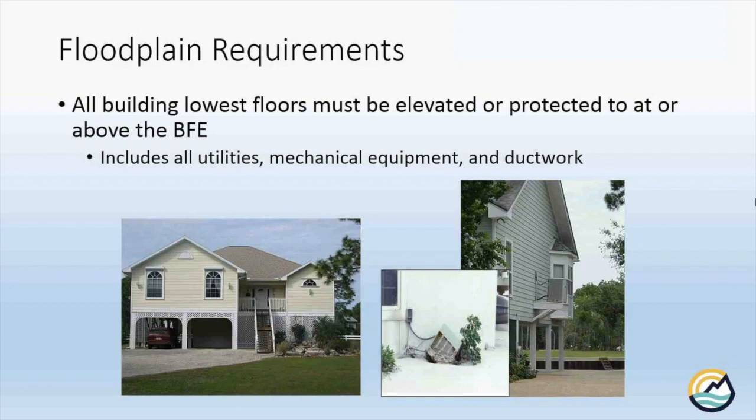Big requirement though, like I said before, all buildings' lowest floors have to be elevated or protected to above the base flood elevation. I'm going to say that again. All buildings' lowest floors must be elevated or protected to above the base flood elevation. So basically we want to keep you high and dry. It's going to flood there at some point, so keep your stuff up above it.